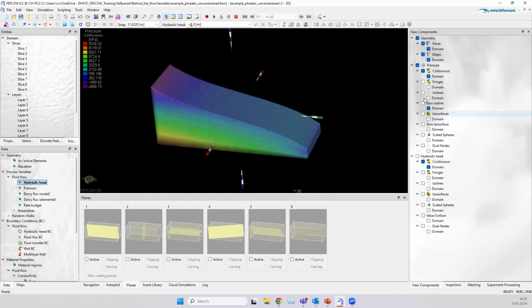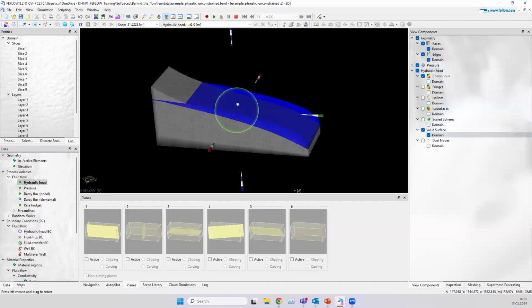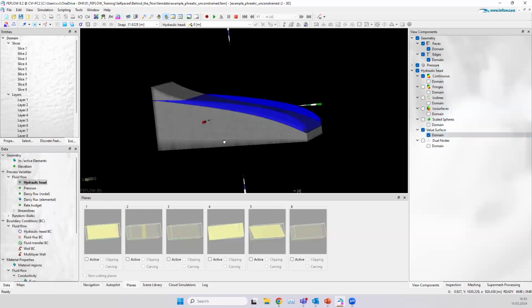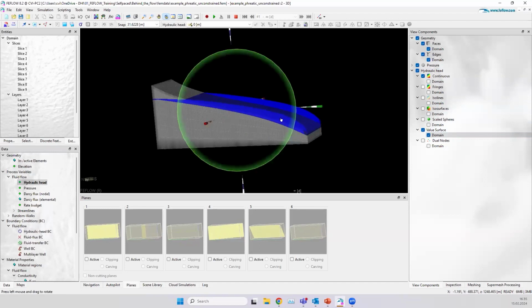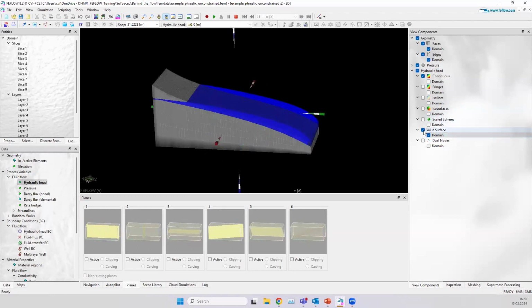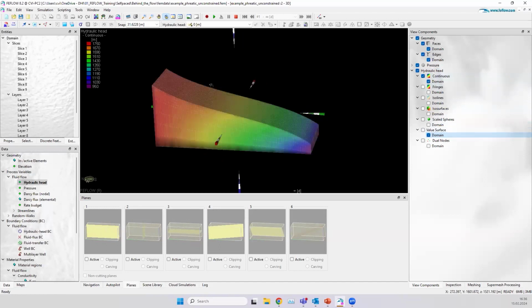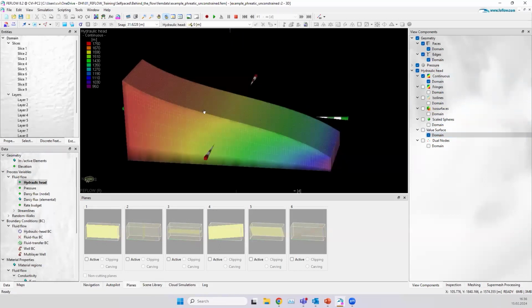Another way to visualize this water table is not much used, or not much known by users, but it's quite practical. We have the possibility to draw a volume in 3D as a representation. Here FEFLOW will encapsulate and tell you, okay, this is the location of the phreatic surface, and depending on the reference systems, it will draw a water table on top. So it's also quite nice to easily identify whether your system is oversaturated or not. This is called value surface. So we see that there is a high potential in some locations, but FEFLOW simply calculates.